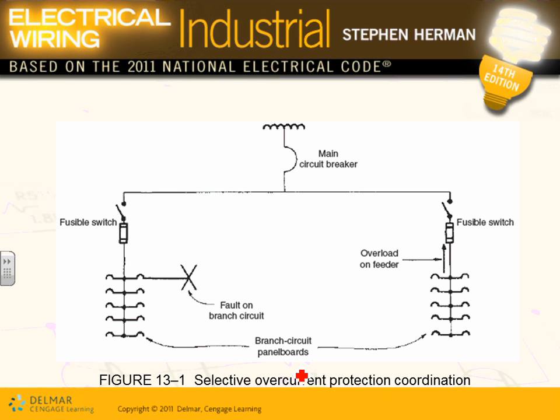Ground fault protection. Okay, so that's what you have, guys. You have a circuit. Here's my main circuit breaker. I have a fuse disconnect overload on a feeder. So if this circuit breaker is 1,000 amp and the voltage is 480/277, I am required to have ground fault protection for equipment on this circuit breaker.